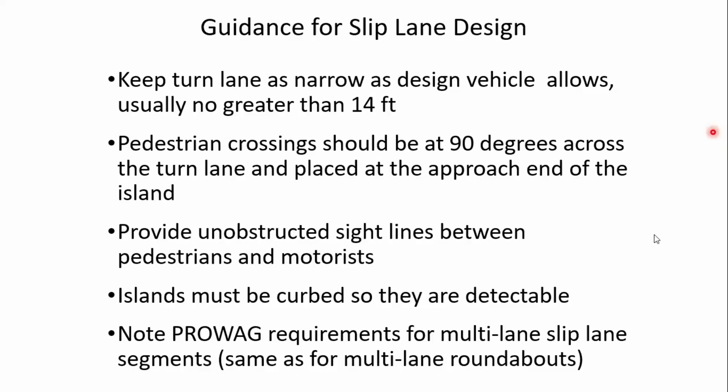And I recognize there is significant interest in that, and actually a number of communities are doing things in that regard. The main concern I have with that is the visually impaired user, low vision users, who rely on contrast and colors to navigate. For them, something like the continental design would probably be the ideal crosswalk marking, if you will, because there's plenty of white material there, but there's also good contrast with the, we'll call it the asphalt, street paving material.